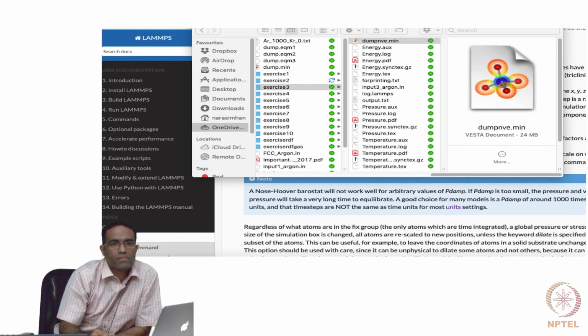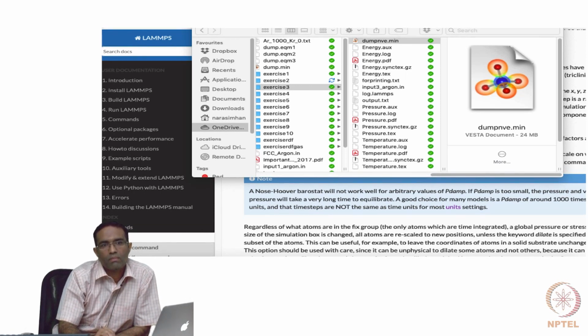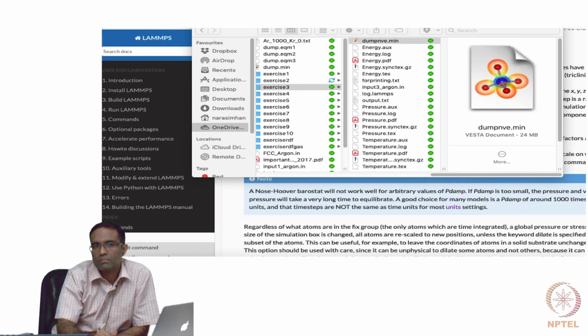So when the system reaches thermodynamic equilibrium, it means that thermal equilibrium, mechanical equilibrium and chemical equilibrium are individually reached. Yes. Chemical equilibrium is reached when chemical potential is the same throughout the system and does not change with time. Thermal equilibrium is reached when temperature remains the same throughout the system and does not change with time.